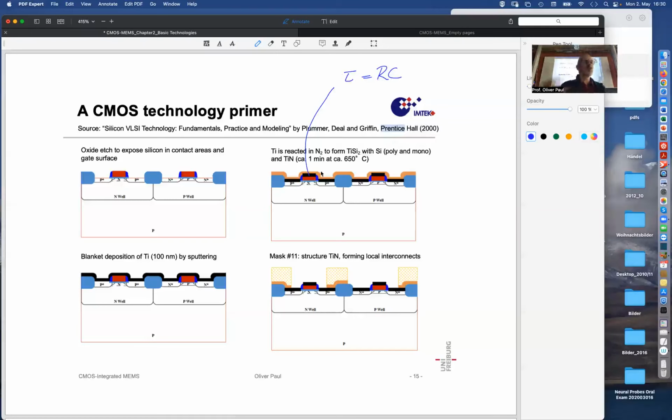There is capacitance all over the place. So the gate oxide, now the gate material, of course, creeps over some field oxide at some point and is contacted, and there is a metal line. And so you have lots of capacitances with respect to the surrounding. There's metal, conductor, insulator, and then some other conductors. So those C's are inherent in the structure. You can't remove those. And so reducing the R as much as possible is important.